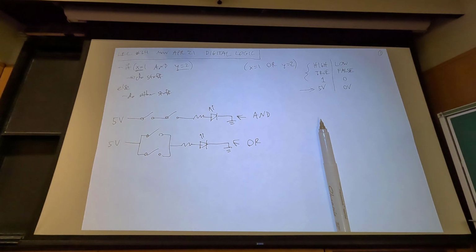If you have 8 motion sensors and you want your Arduino to trigger an alarm if any of the sensors detect motion and go high, right? You could do that using 8 different Arduino pins, have each sensor go to 1 pin, or you could combine them through a bunch of OR gates and then just use a single Arduino pin.